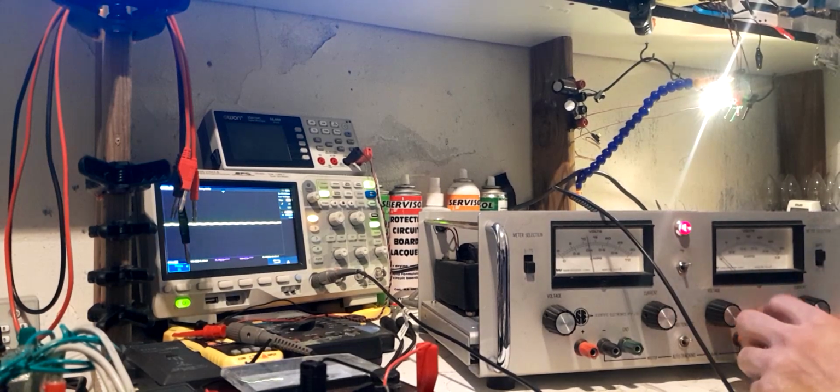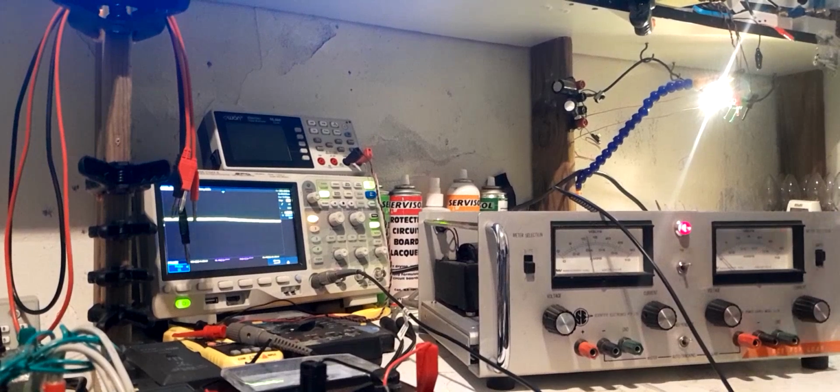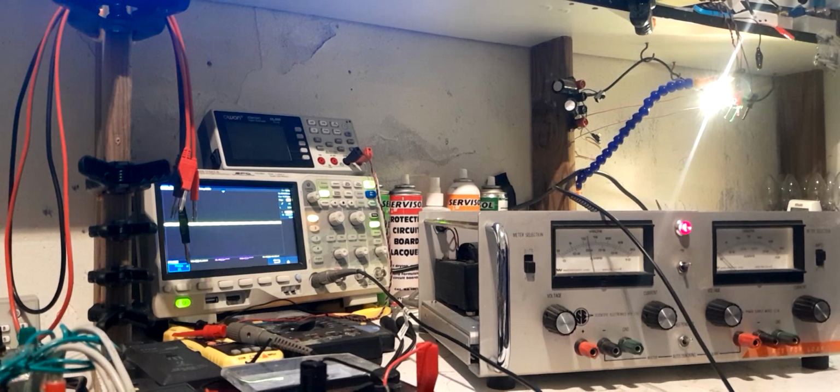So that's good. And as we saw with the references, I put 47 microfarad caps on them and that cleaned them up a lot. I tried holding one microfarad MKT across it and that cleans up a lot too. So I think what I'll do is put them back in with 47 microfarad caps and 1 microfarad MKT.